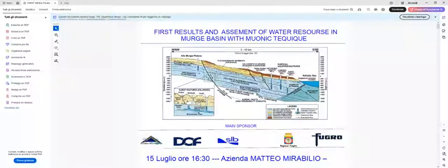The second part is the central part of the aquifer that is delimited by the normal Cretaceous faults, and this is the low part because it is filled by flysch sediments and plio-quaternary sediments. You have the calcarenite of Gravina and you have the Pliocene sediments in this part. So we have different types of circulation and ways of recharge of the aquifer.